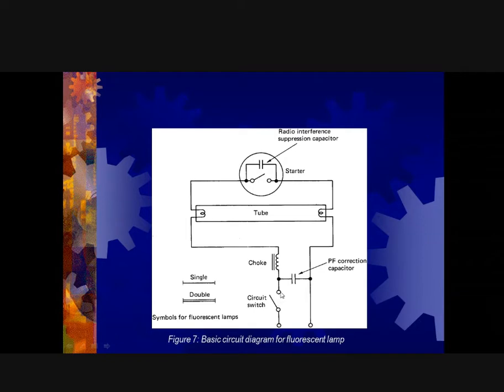Here we have the switch closed. Our initial sense is that for this circuit, the choke, in terms of the inrush current, will reduce the inrush current while applying a large voltage. So it will ramp up the voltage, because of the transformer involved in the starter, in the ballast, and then what will happen is that the high voltage is going to be present across the tube.